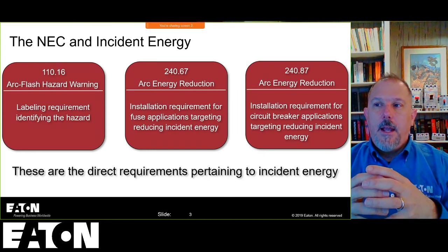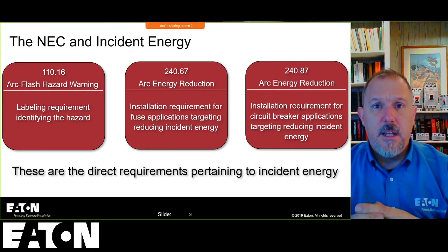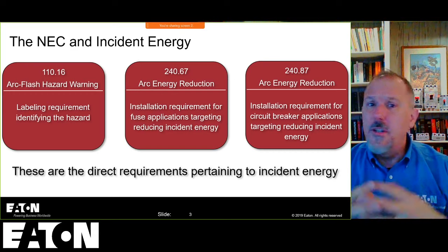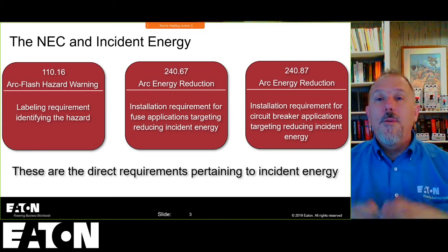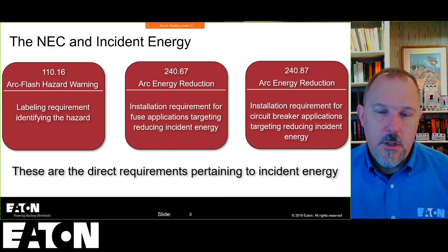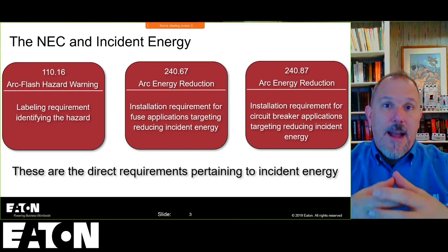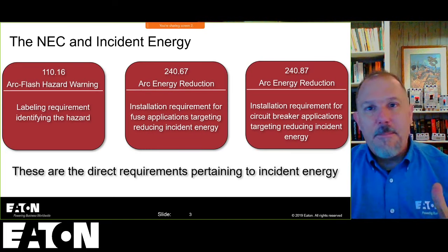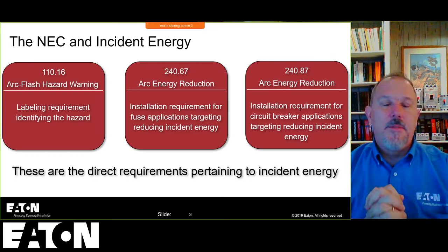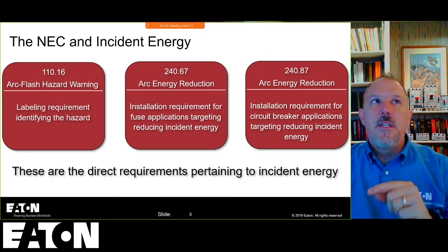And if you have a fault downstream, I defy it, especially if you're in the instantaneous region, you're not going to get line side propagation. If you're outside of the instantaneous region of a breaker, or outside of the current limiting region of a fuse, you're going to get enough plasma probably in the air to propagate. But I would almost argue that in that case, with that wrapping, the chances are much lower. I can't say it would never happen, and I can't prevent a fault from occurring behind that, but what are the chances of that as well? I believe, though, that change increased safety considerably.